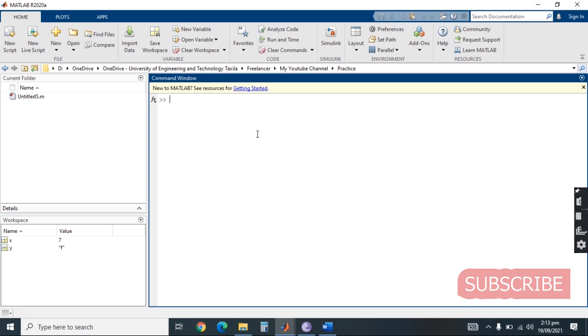Now we will see how we can plot our data in MATLAB. Now for the plotting statement, and we'll learn how we can make a plot in MATLAB. To learn the basics of plotting, we will first learn how we can declare arrays. Let's say we have two arrays with the names x and y. When assigning values to arrays x and y, it must be considered that an equal number of values must be present in both arrays if you want to perform any mathematical or plotting operation.